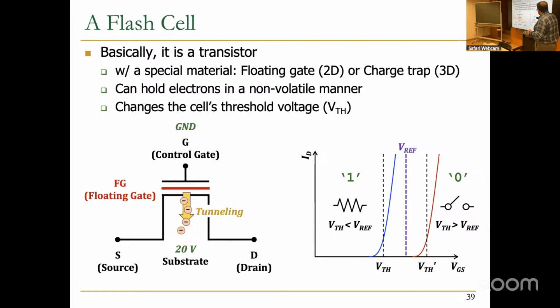So the thing is that when you program, you have 0, for example. And then you want to write 1, there is no way to write 1. You need to erase it. And that's the process of erasing, where you apply a negative programming voltage, like minus 20 volt, in order to tunnel these electrons back to the substrate and then get to the nominal threshold voltage that you had.